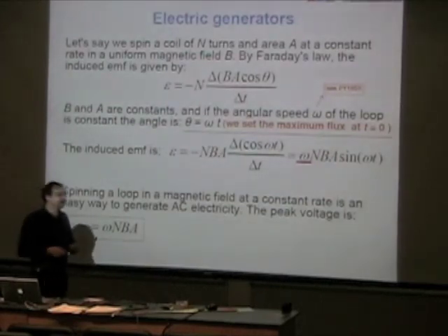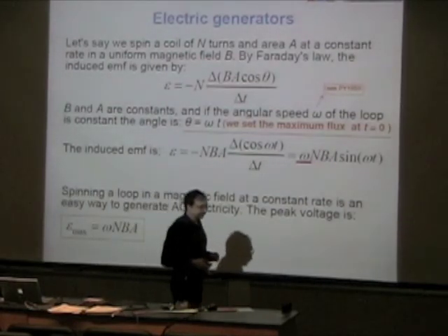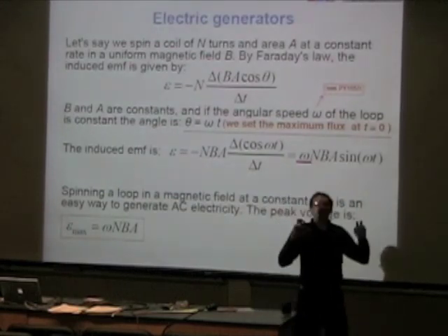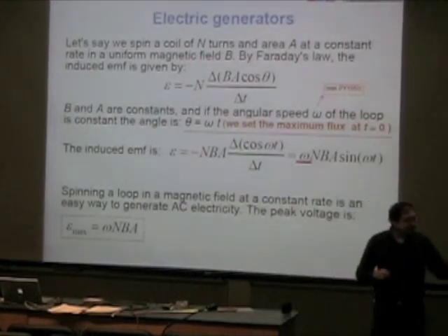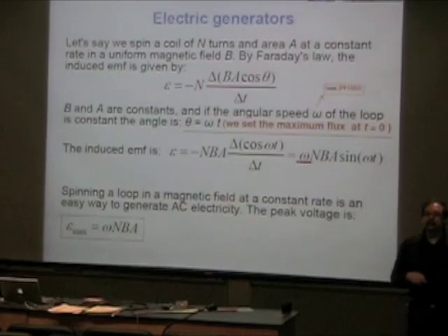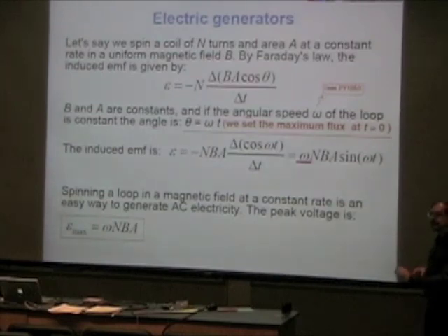To describe, well, let's say some reasonable value. People don't use maximum values. People use maximum value divided by square root of 2. Well, there's a reason for that. So if it says 120, that means maximum value will be 120 times square root of 2. The name for this is root mean square value, RMS.